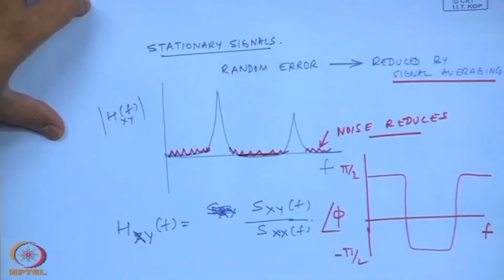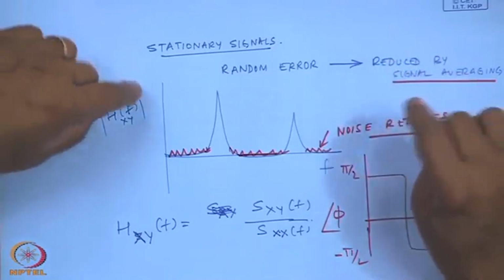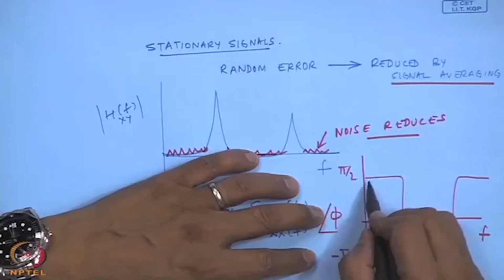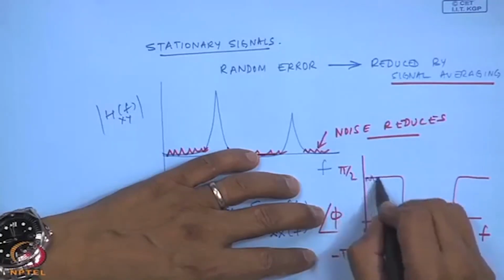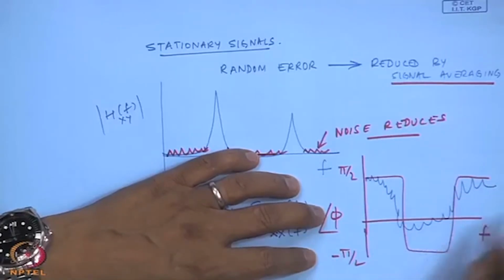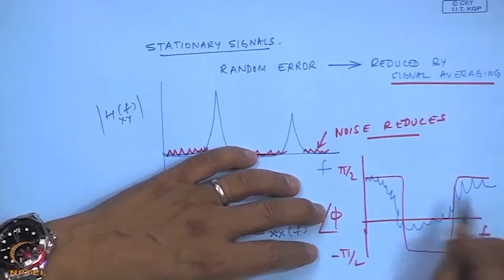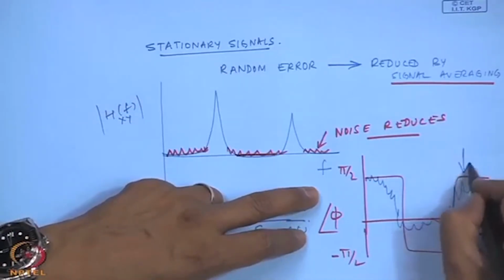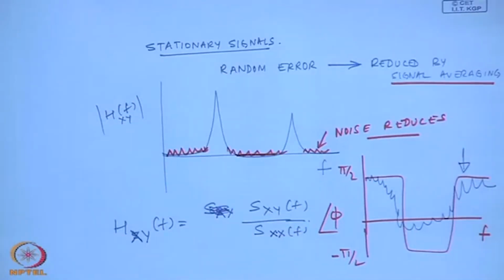However, when you do such analysis between two signals coming from a machine where there is a lot of looseness, this phase will make no sense, because if you do an average, you will not get any meaningful information. That is what I mean by unstable phase between signals. So, these are clear indications that a system has looseness.